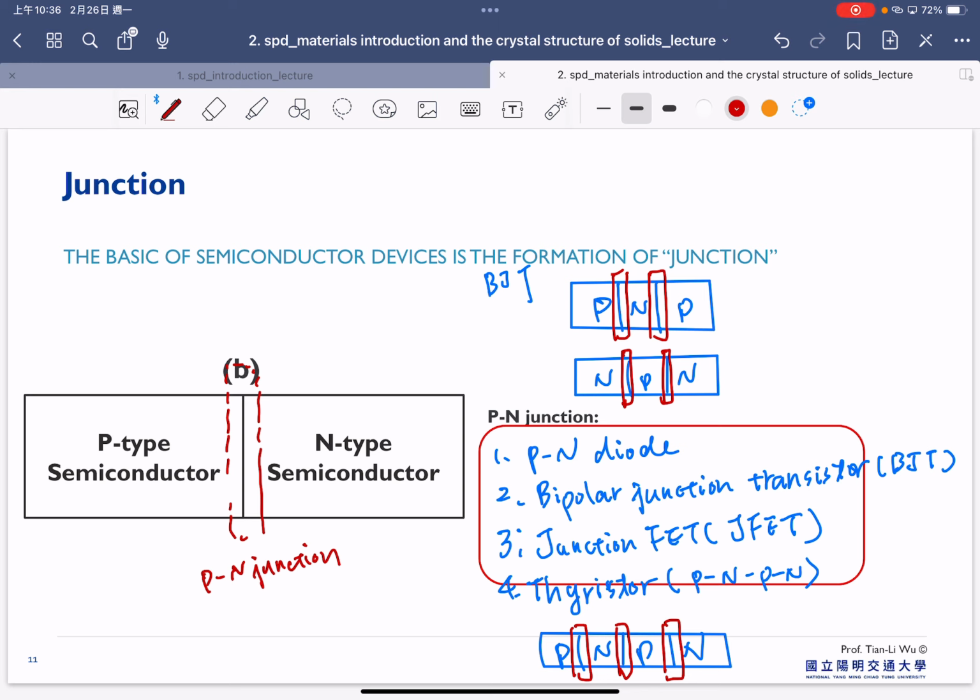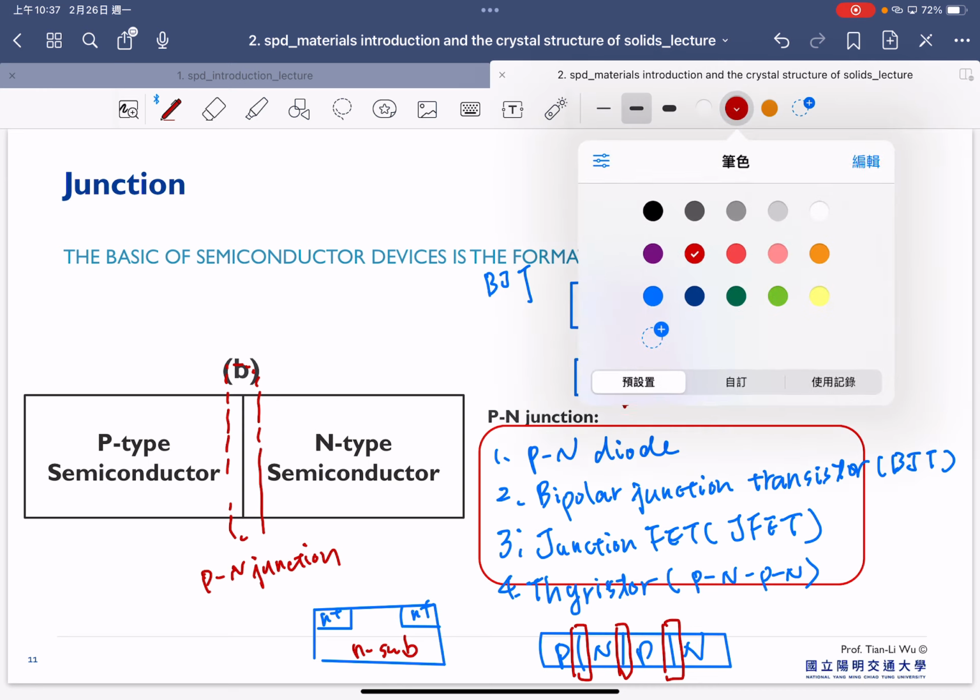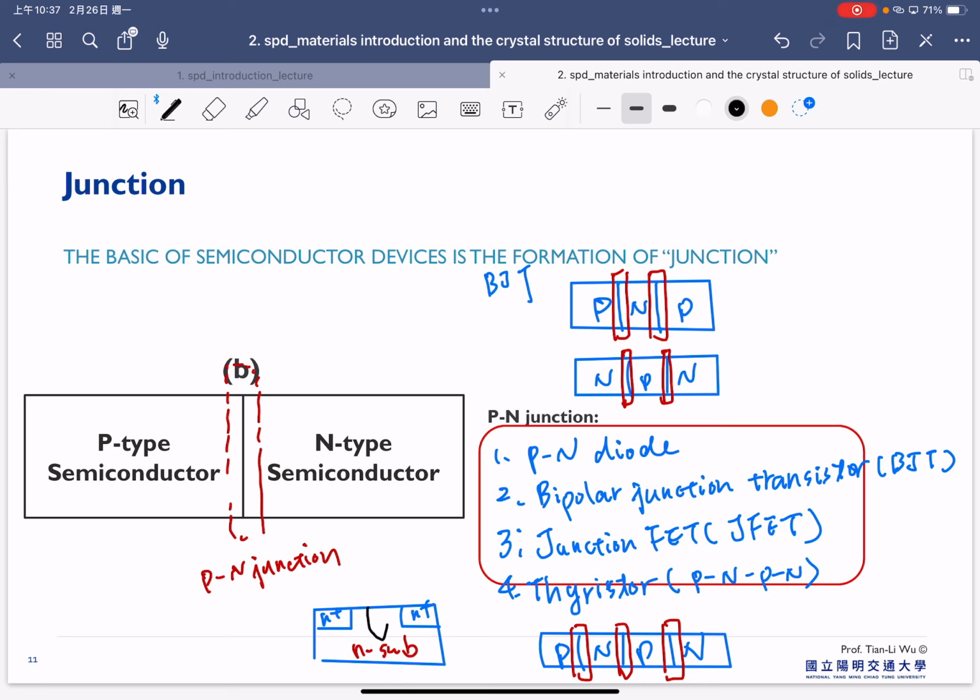And in the case of the JFET, the JFET structure looks like here. So we have the N plus, and first of all, this is an N-type substrate here, and in the JFET, we don't have the oxide here. In the channel region, we make this part a P, and we apply the VG here.